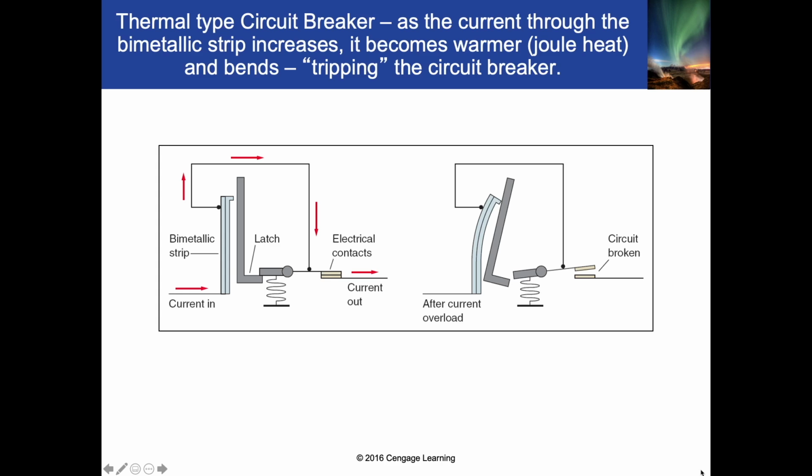What does that remind you of? It should remind you of something that I asked you about on the last test. Yes, the thermal expansion of brass and iron, right? The thermal expansion of brass and iron. And so the reason why it's bimetallic, right, is one of those metals has a larger thermal expansion than the other metal. So when it warms up, it bends. It doesn't just extend and get longer, but it actually bends. And it has to do that, right? Because if it didn't, nothing would really happen. If it extends, it just gets longer. It doesn't actually do anything.